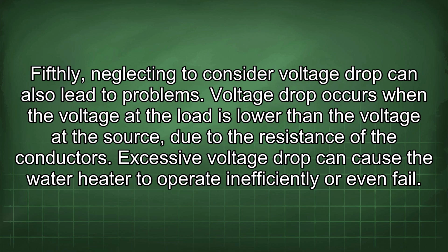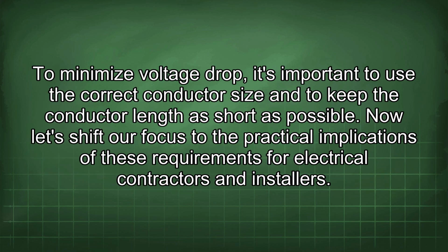Excessive voltage drop can cause the water heater to operate inefficiently or even fail. To minimize voltage drop, it's important to use the correct conductor size and to keep the conductor length as short as possible. Now let's shift our focus to the practical implications of these requirements for electrical contractors and installers.